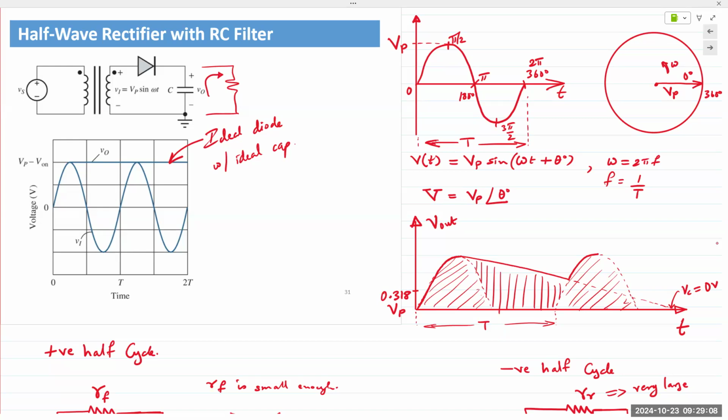That energy right here is coming from the stored energy of the capacitor, because the capacitor is where we are taking the output. Does that make sense to everyone? It's the discharging portion of the capacitor, so the capacitor is supplying its stored energy to the output, and so now your DC level has risen. Because the DC level has risen, we can now consider this waveform as an actual DC waveform.